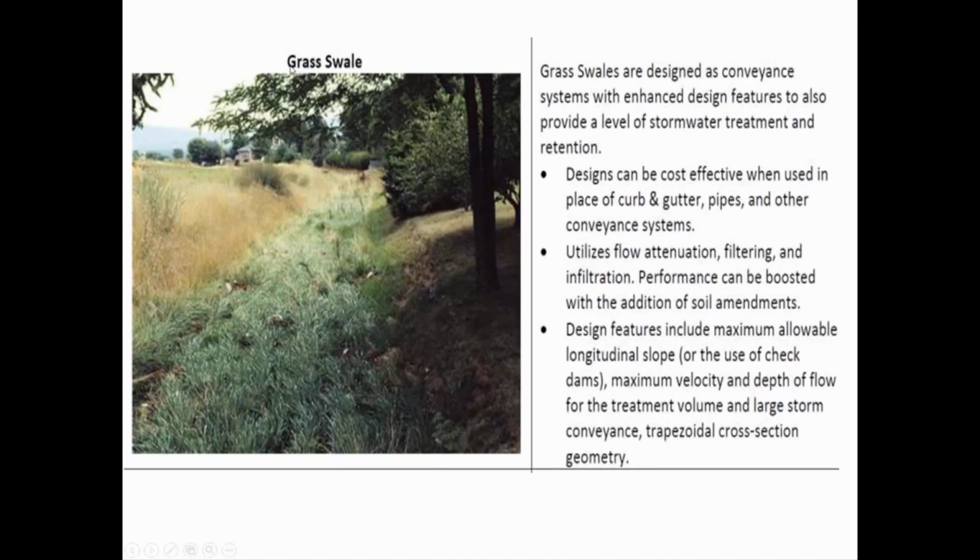Okay, a grass swale, that's a fancy name for putting grass in the ditch. So why would a grassy ditch be better when it comes to fighting the effects of urbanization? Why is a grassy ditch better than just a dirt ditch? Slower, exactly. It's because this grass sticking up into the flow has a higher n value, so the velocities are going to be decreased.